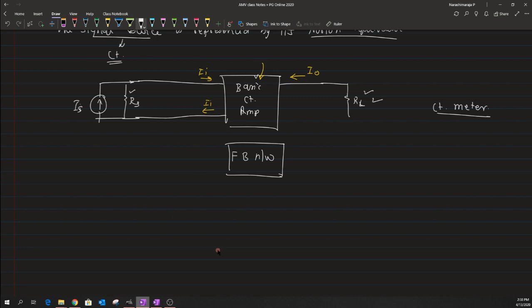So in a way, say for example you just want to measure some sort of current, what you generally do is that you just apply your current meter through a kind of series connection. What we really mean is that if I have an ammeter, you put it in and then the current flowing through the circuit or wire is read like this. Okay, so the same wire is fed in and fed out.